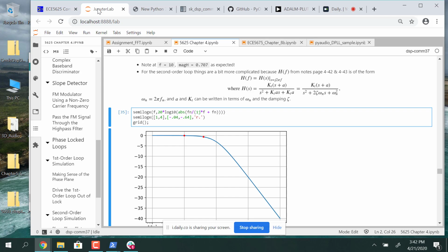There's a few little things you got to figure out, but it's not too bad. So you're learning how to do a Bode plot in the S domain, which you've had to do already in other instances, I believe, and then put some experimental data points over it. The reason they're experimental is because you're running this on a loop that is a nonlinear control system, and you just can't easily set up a system to sweep the frequency response.